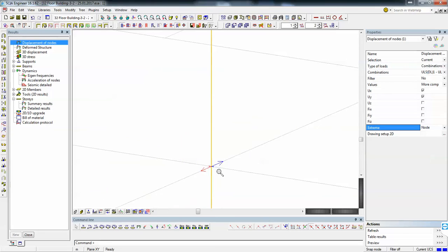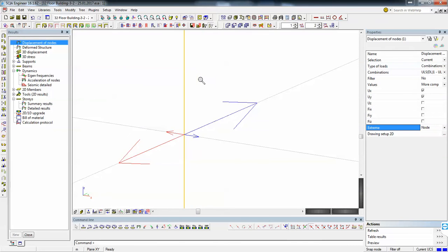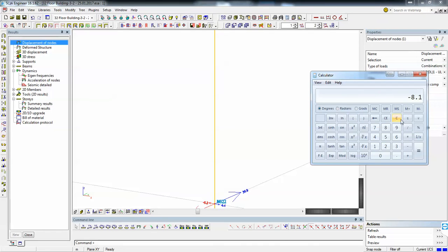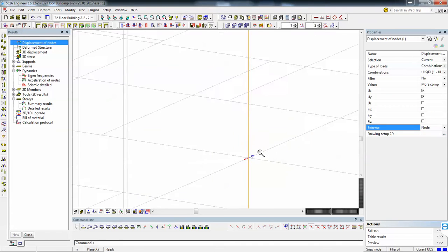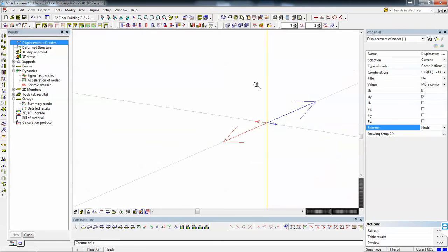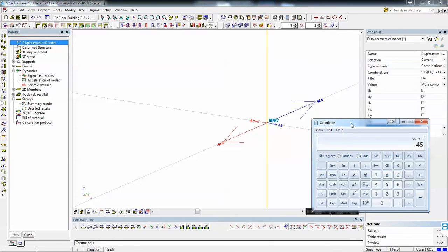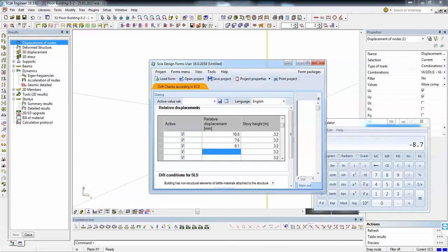This check is normally for seismic action. This is why it's implemented in SIA automatically for seismic action, but for wind, although it's not imposed, it's a good way of checking whether the cladding will be affected or not. So it's a conservative approach which will ensure the safety of the glass. So anyways, as far as I see, it's not affected. It seems that there's no problem.